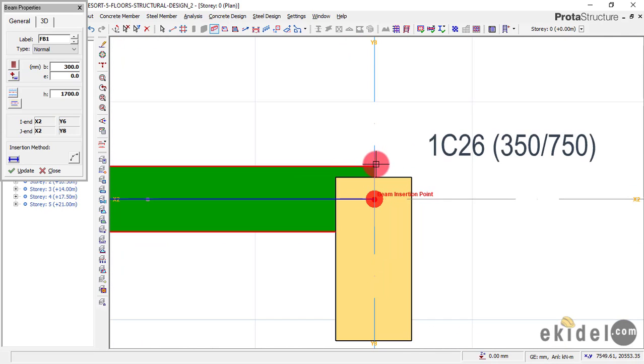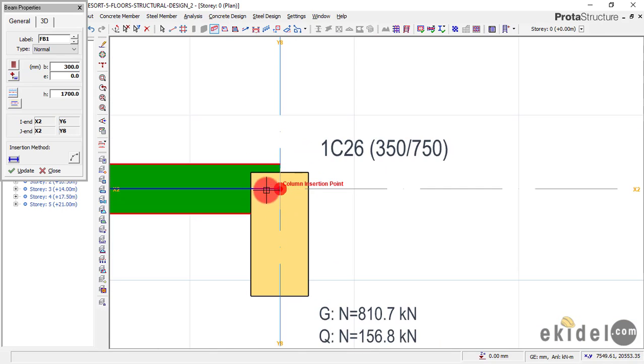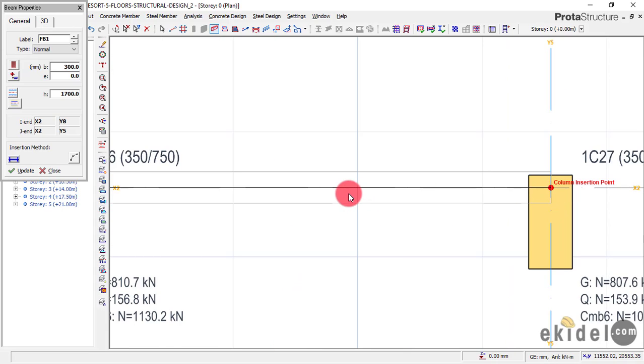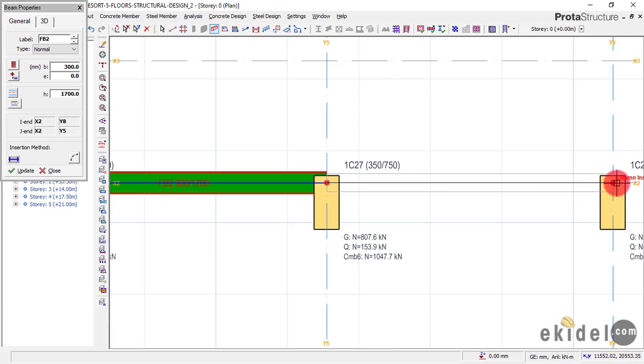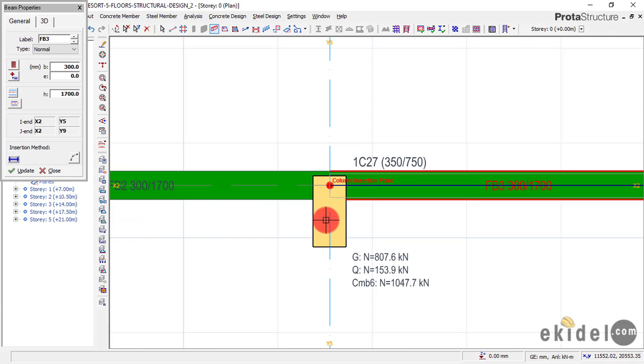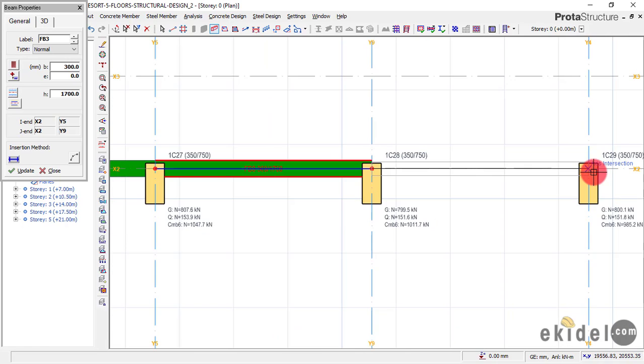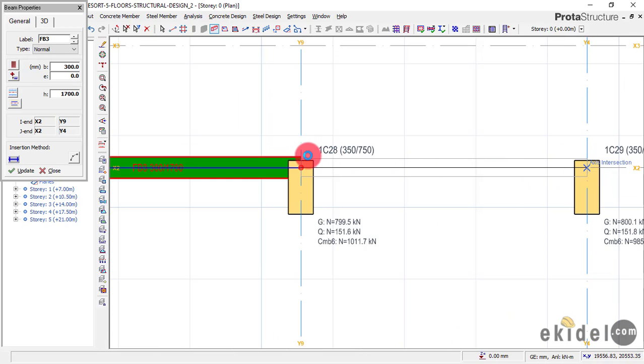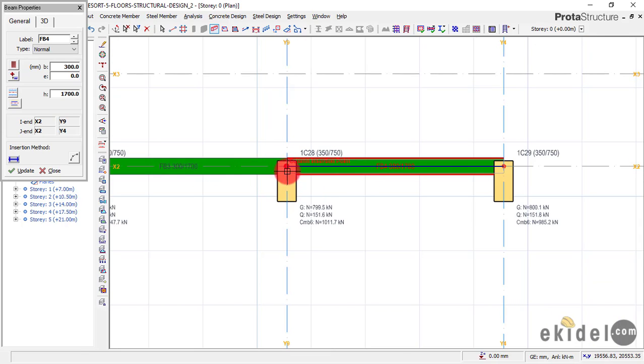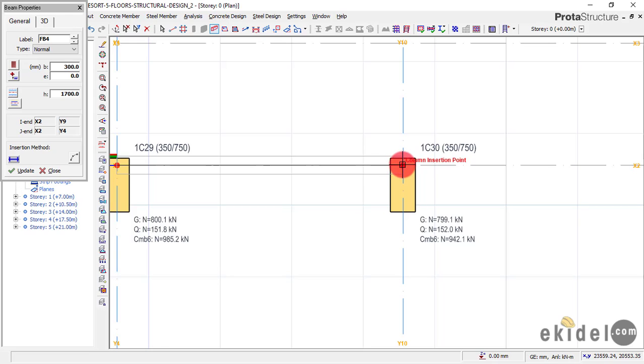This doesn't bother the foundation basically. So the raft beam can be bigger than the column in width. It doesn't matter, but the whole idea is that the beam property should be able to carry the weight of the structure. That is the only thing. Okay, so right now I'm not bothered about this, so I'll continue again and keep this here, and continue again and keep this here. There was a reason why we have to push the columns inward. That is why if you watch the 5-story building design course video, you will know why we did this. Okay, so right now I'll continue again to keep this here.